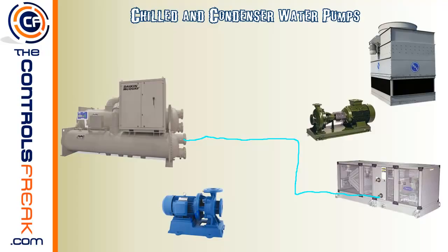of the coil. And the reason why is you want this to fill up with water before trying to pull it out. It's possible if you were to supply this coil with water coming into the coil from this direction, that the water may not actually fill the coil and you'll get air in this coil, which would mean that you're not going to get cooling on the upper portions of this coil if there was just air there, and water would flow in and then come down and get sucked out the bottom. So the reason why they fill it up from the bottom is that way you make sure you pressurize the coil and get all the air out of that coil. Alright, so we've got the chilled water coming at the bottom of the coil.